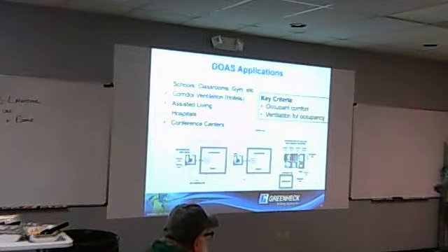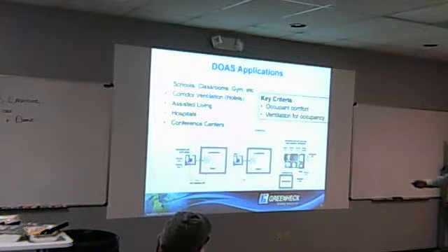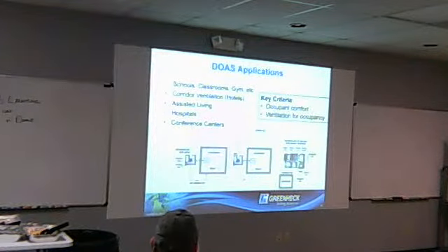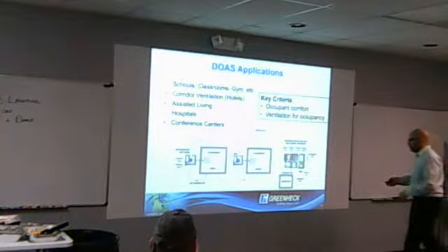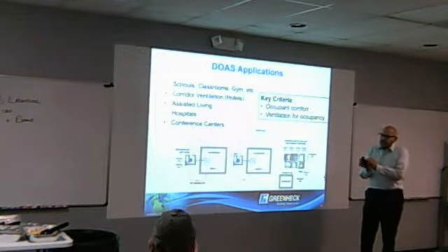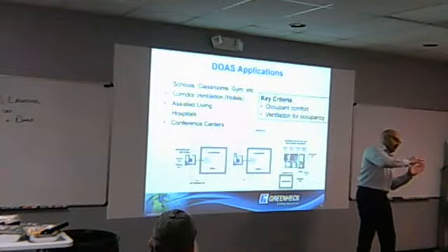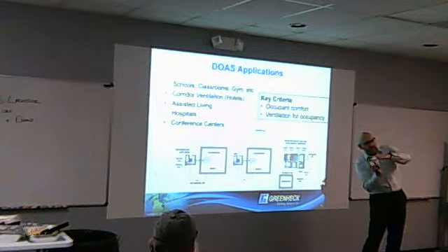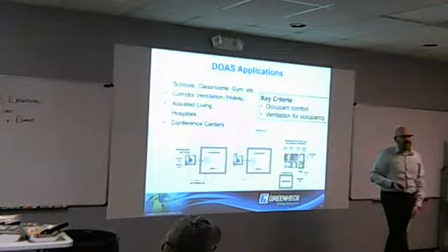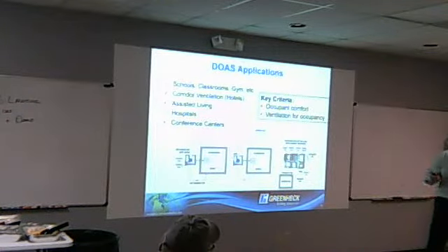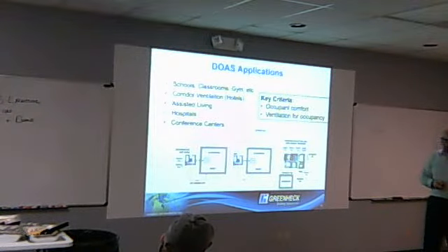If somebody wanted less, we could do some cores in there instead of the wheel. But in terms of the wheel and the seals, we've seen as low as 1%, but we allow like that 3 to 5 in terms of a discussion point, and it hasn't been a problem. Some people will add a purge section, which takes part of that outside air and turns it back to purge the wheel before it rotates from exhaust into the supply. If they're concerned about it, that's an option. Generally, not a big deal, but we have ways to address it if somebody is concerned.